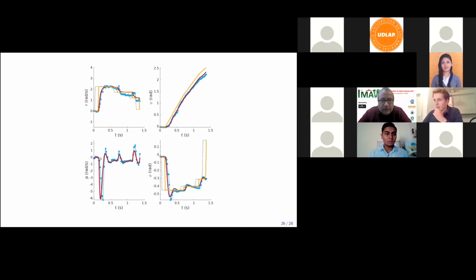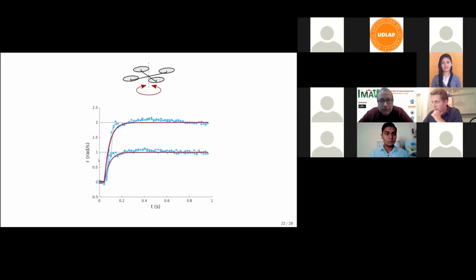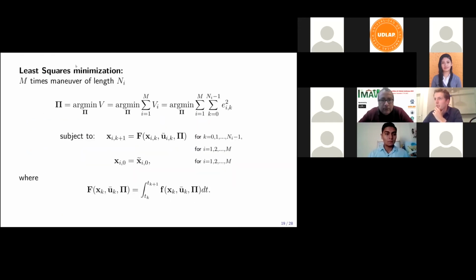If I understand the question correctly, the question is, what's the difference between using least squares in this minimization or using a Kalman filter for parameter estimation? For me, this is close to what I will actually be doing in a model predictive control context, where you simulate your system over a horizon in the future using the nonlinear model, in this case also a fourth order Runge-Kutta system.